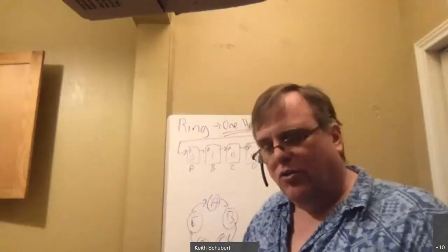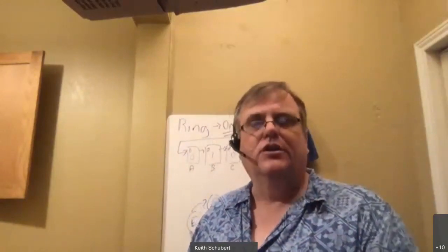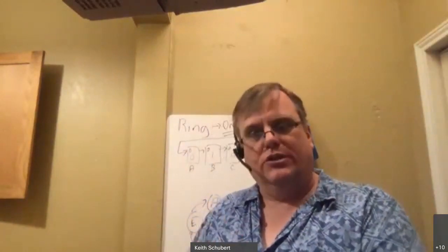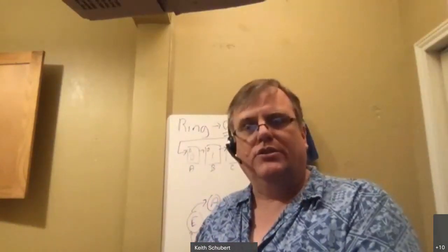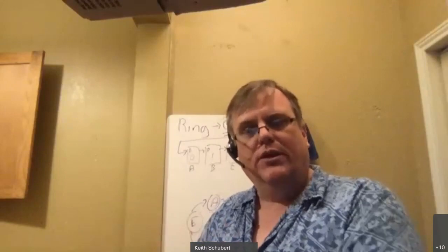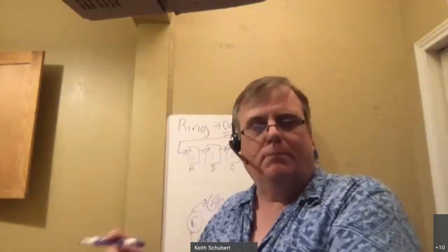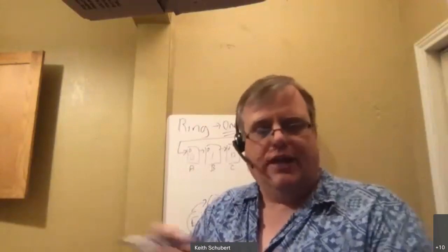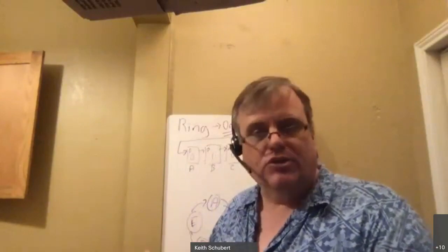We're going to break it down in intelligent ways to simplify it, and we'll have different stages that will handle things. Get an instruction for me, we call this fetch. Figure out what the instruction is, we call this decode. Actually process the instruction, we call it execute. Access memory to get data for me, that's the mem stage. And then there's what's called write back, where you resolve the answers and store them in the temporary storage area, that's your register file.